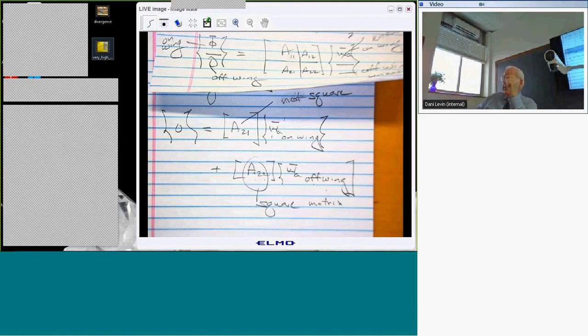And what is true is, when you go into the wind tunnel and make measurements, the pressure does not go to infinity, right? But it does get really high. In fact, usually it gets so high that it's hard to measure the pressure near the leading edge in a wind tunnel experiment. So everything works out more or less.